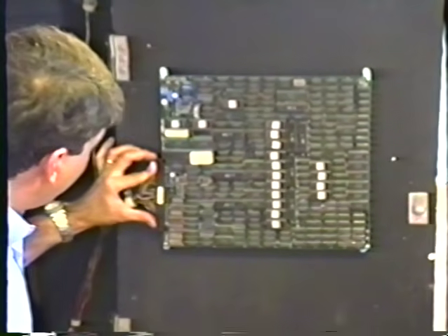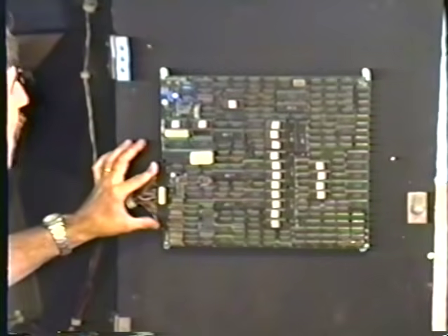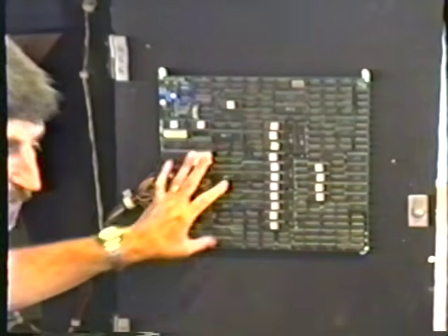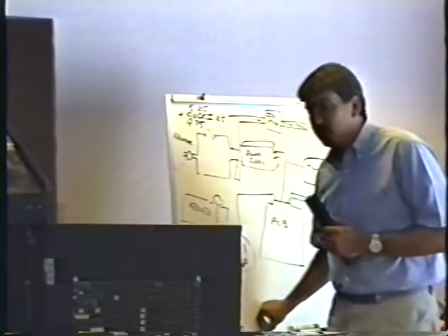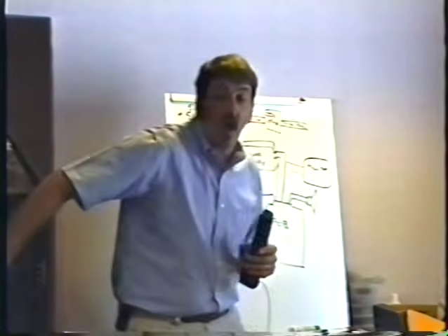Well, the important thing is to check the voltage on the logic board itself. I don't really care what it is at the power supply. I want to make sure that it's exactly 5 volts on the logic board.